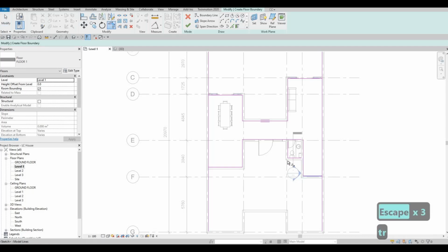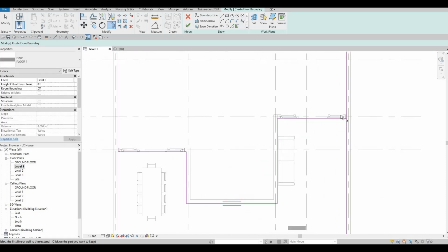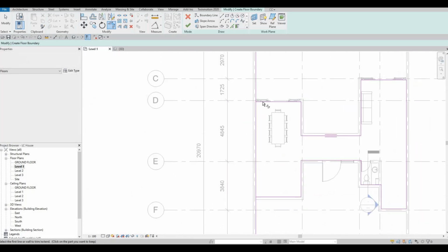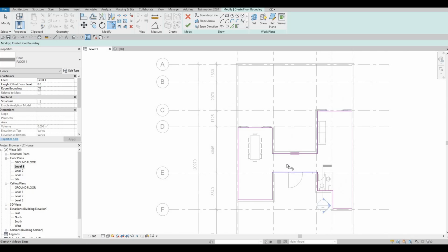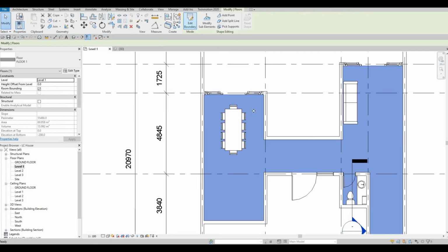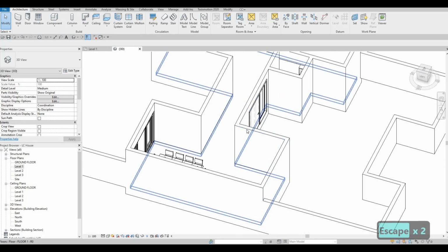So now TR, that's trim and extend. Go to all the corners and make sure that you trim and extend. It's like fillet in CAD, and it's basically just cleaning every corner up. Everything is selected, and nothing is overlapping. Once you do, you just need to click finish. If there's an error, if you forgot something or something is overlapped, it will let you know. So right now we did it perfectly. We have the floor right now.